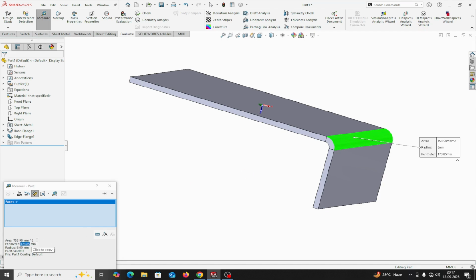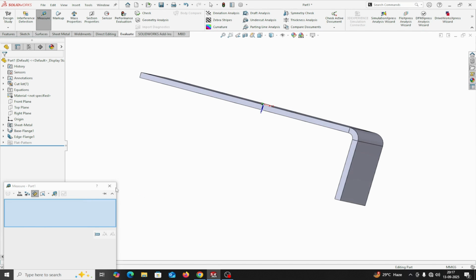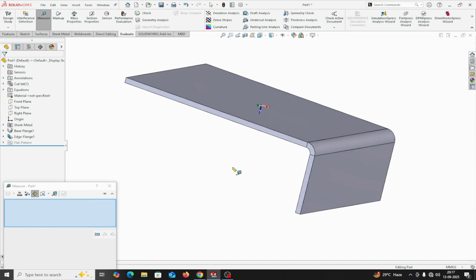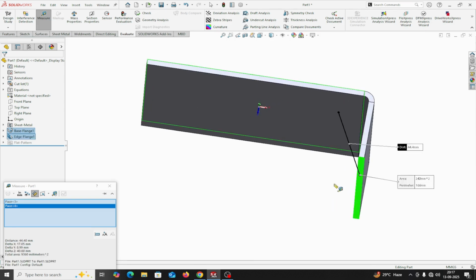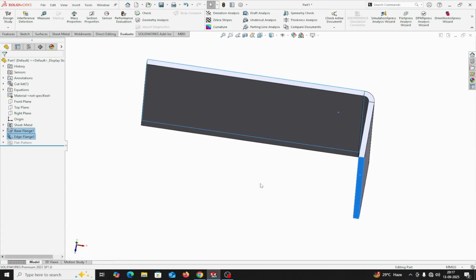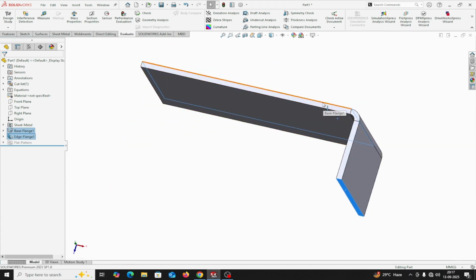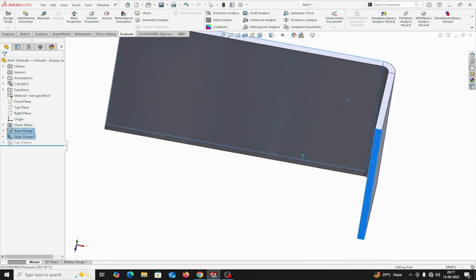You will see this is 6 mm thick. And if you take the height from this surface to this surface, the height will be 40 mm. You will see delta Z is 40 mm. This height is from the intersection of the outer edge and the outer edge of the flange. The height is taken from this to the parallel end.